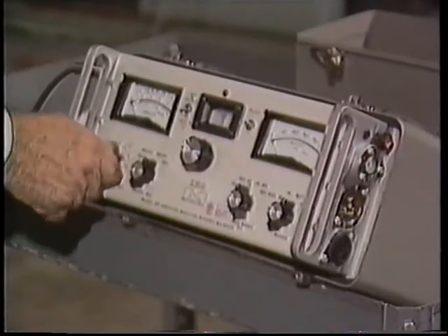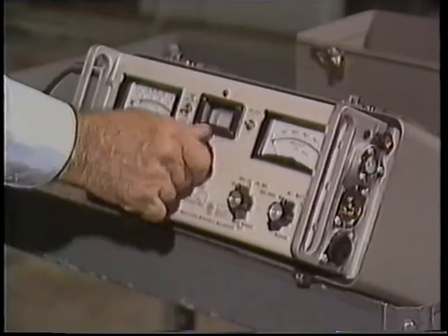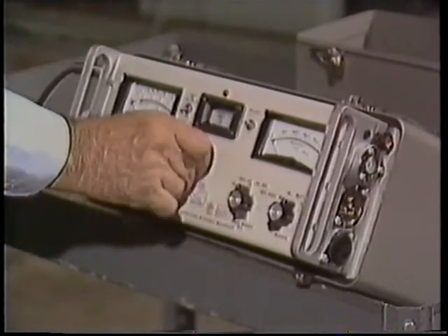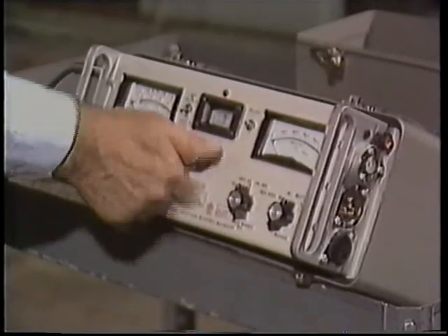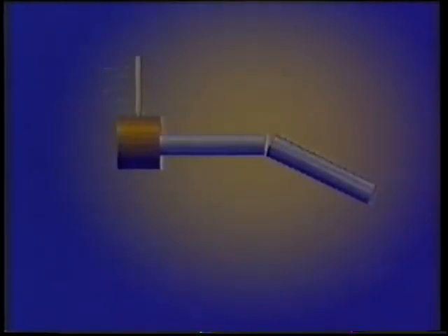You'll recall that unbalance also occurs at 1 times shaft RPM. To determine whether the problem is caused by unbalance or misalignment, you need to look at the direction of vibration. For example, vibration produced by angular misalignment will be indicated by vibration amplitudes both radially and axially. That's because vibration travels outward from the shaft's coupling. But because the shafts are rotating at an angle to each other, vibration also travels down the length of the 2 shafts, causing axial vibration. Unbalance, on the other hand, is primarily radial.